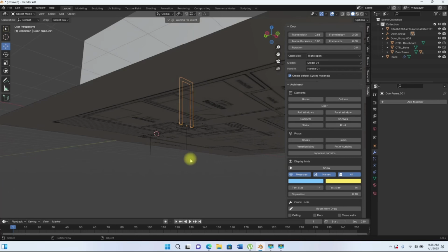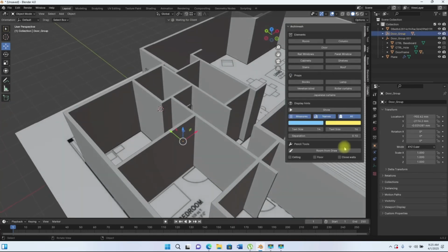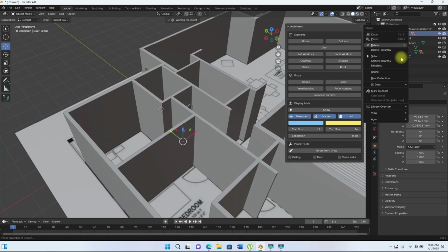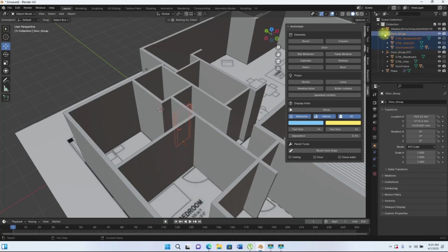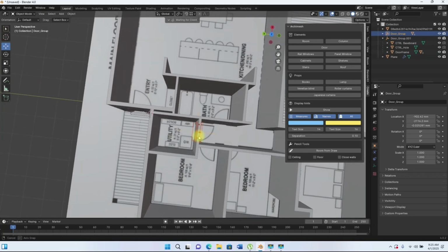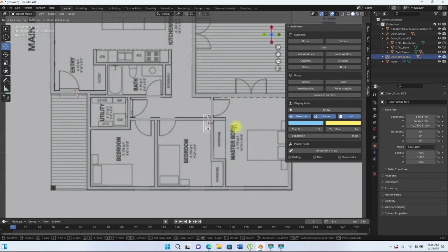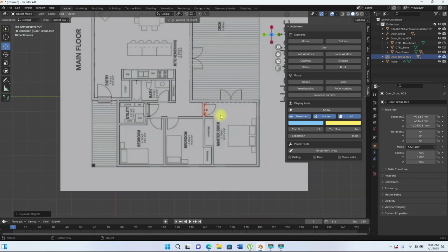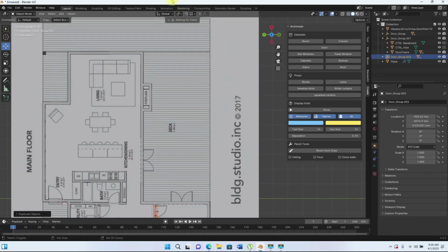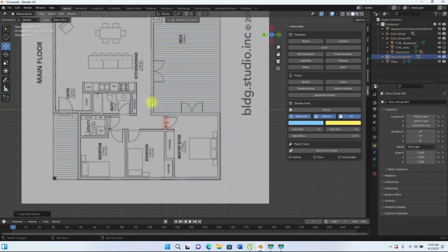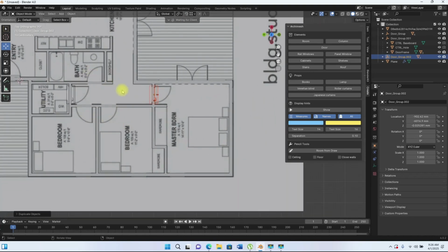So what we'll just do is select this door, and while it's selected, right click, select hierarchy. So it's going to select every one of the children inside it. So while these guys are selected, if I go to my top view, I can duplicate and position them appropriately. So Shift D, have a duplicate. I'll put the duplicate here. Press my Y so that it's going to constrain it horizontal that way. So we have that. It's still selected, right? So we'll have to duplicate to different places again. So I still need like three more. One, two, three for all the interior doors.